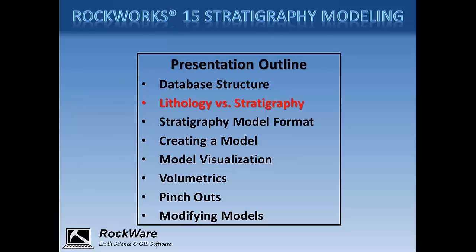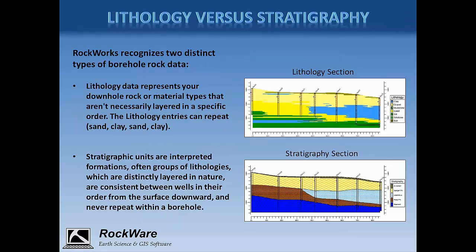between lithology and stratigraphy. There are significant differences in how lithology and stratigraphy data are modeled, so it's important to be sure that you're using the correct database table and modeling tools for your data. I typically describe lithology as your observed material type, and this could be rock or unconsolidated sediments. For example, if you're logging a hole and you observe a 10-foot section of interbedded sands and silts, you would probably log that detail in the lithology portion of the database.